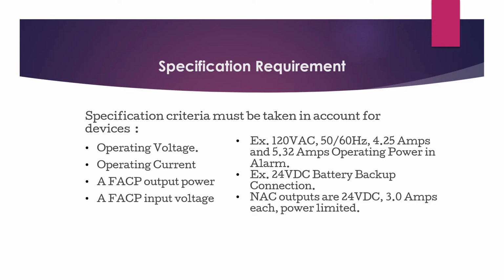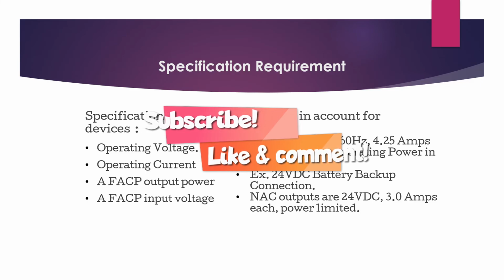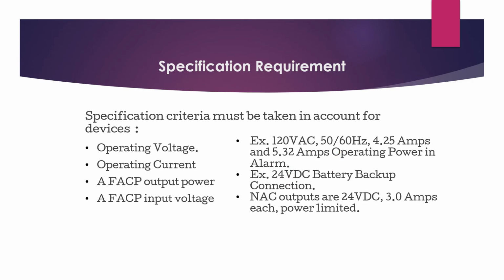And further, we can look into what we call the alarm power, and look at the battery backup connection. There are a lot of fire alarm panels that come with an emergency power source, just in case we lose power coming from the main. The number one issue when working with a fire alarm panel is that the power may be affected.